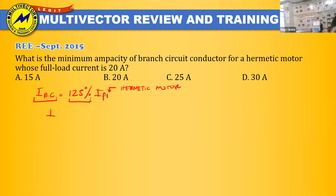Therefore, the branch circuit current is just equal to 125% multiplied by the full load current of our hermetic motor, which is 20 amps. So the correct answer is 25 amps.